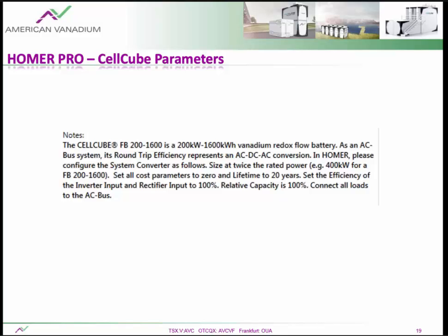So for the converter, you'd want to set it to 20 years life just to match it with the CellCube, and also 100% efficiency, just to make the converter aspect negligible, since the efficiency is already considered in the CellCube add-on.